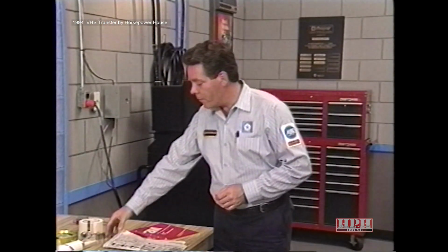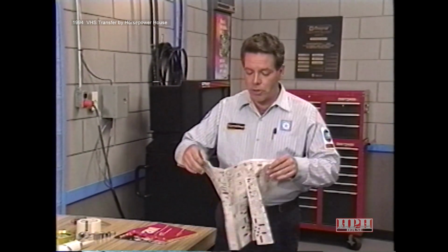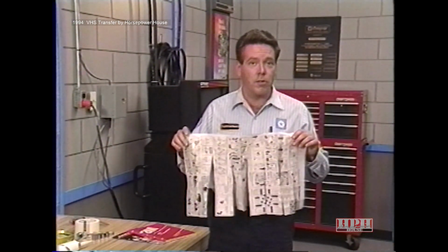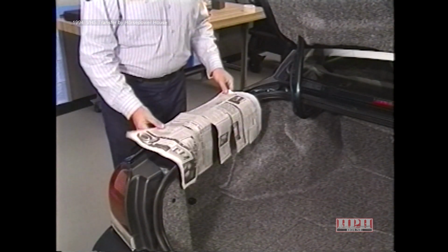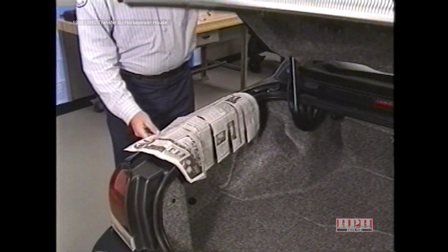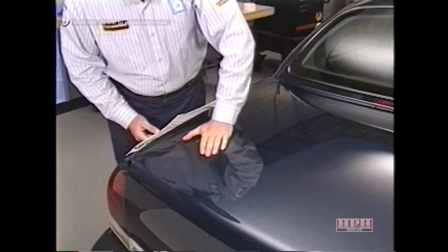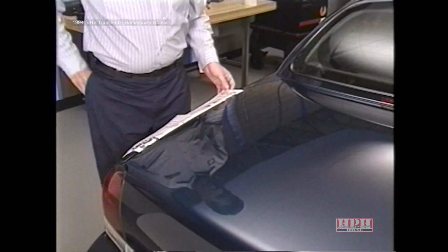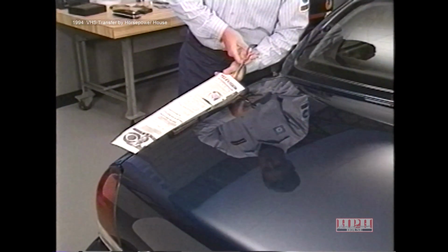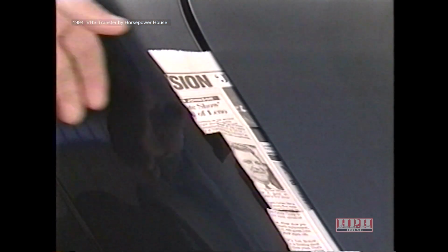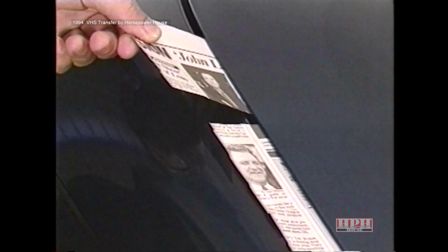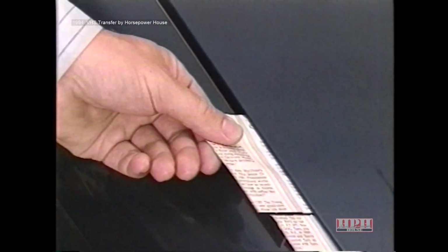An alternate method is to cut strips approximately 2 to 3 inches apart in a piece of newspaper. Place the paper on the questionable seal with the slits extending from inside to outside. Next, close the mating component and detach the uncut portion of the newspaper. Pull the paper out one strip at a time. If one piece pulls out with less resistance than the others, you've found a possible leak.